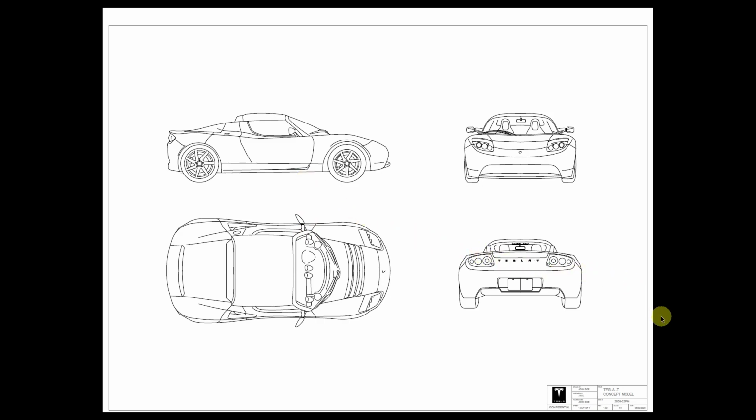All right. So to recap, we created a DWT file, a drawing template file with a company logo and a title block in 2 different sheet sizes. You can reuse the DWT file that will have your title blocks and logos in your future drawings. And we have scaled the drawing to a standard scale. Okay. You could go ahead and modify the scale, the title, and so forth, so they are already available for you. I hope this video was useful for you.